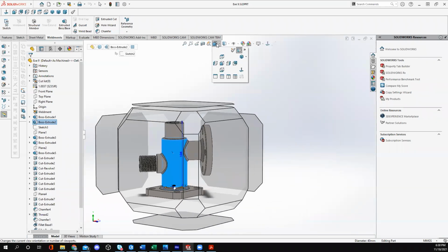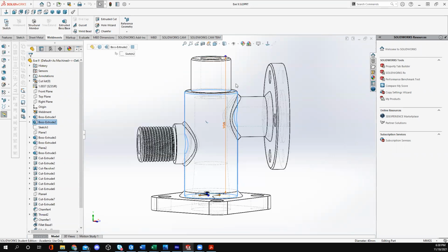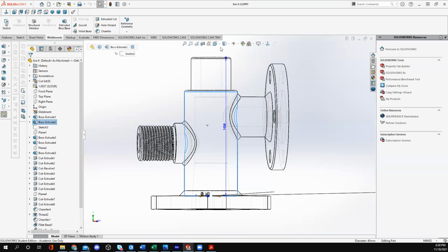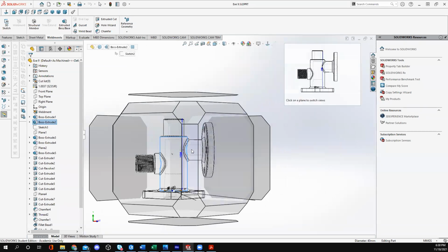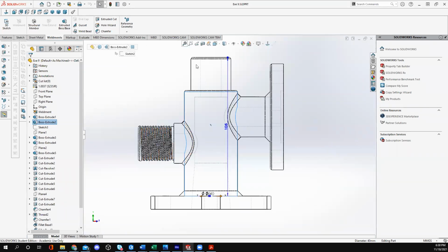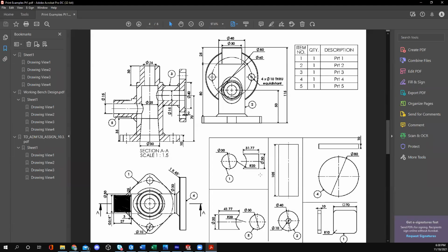I'm curious. I kind of want to figure out how to do my cross section view through here. What I could do is hidden lines, which gives you a little bit better idea. If we go to that corner there, you can see the hidden lines through, and that gives it a better idea because you can see the internal geometry of everything. So it's not a true cross section, but you can see where the internal shape of this object would be. Gives you essentially this idea here.